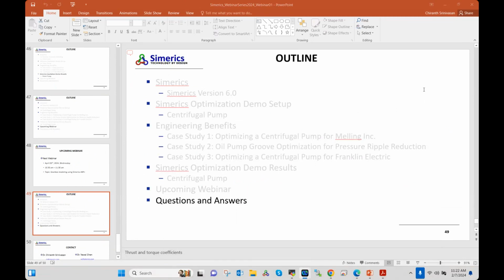From Todd Moser, I'd be interested in how you define the moving mesh for the piston pins and the connecting rods. So we have an expression-based editor, which is our native scripting, where we write expressions to do some of the moving meshing and squeezing meshing that I showed you. But for this piston pin motion, piston rod motion, and also the crankcase, we have already developed something that can be utilized. We don't need to write it from scratch. It's already there. We just need to modify some of the input terms. So if you're interested, please contact me and I'll get you the correct material.